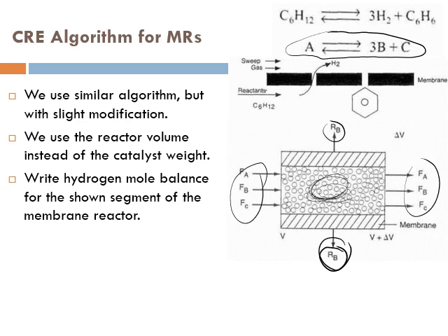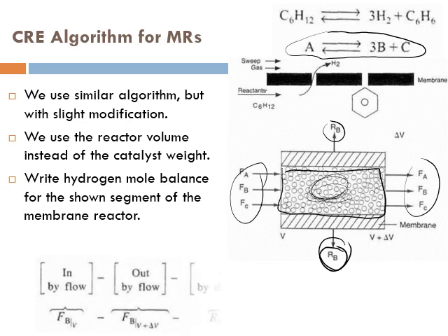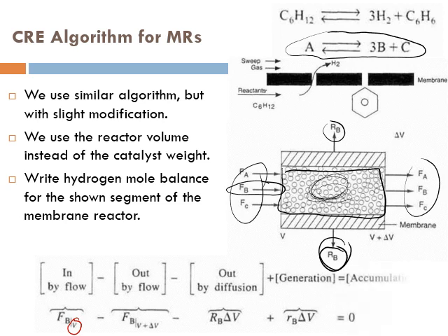So we'll be generating some hydrogen anyway. For a non-conserved quantity, the balance becomes input minus output plus generation equals accumulation. So let's write that. Let's take the input to this control volume for B. The input is FB, evaluated at V, correct? And what about the output? Well, you have FB also leaving here. So not only is FB entering, it's also leaving here, output by the flow. So it's minus FB, however, exiting at V plus delta V.